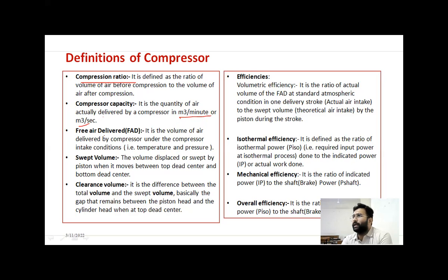Next is free air delivery, or FAD. It is the volume of air delivered by the compressor under the compressor intake conditions. The definition is a bit difficult to understand. So what is the compressor intake condition? Generally they take it as a 1 bar pressure